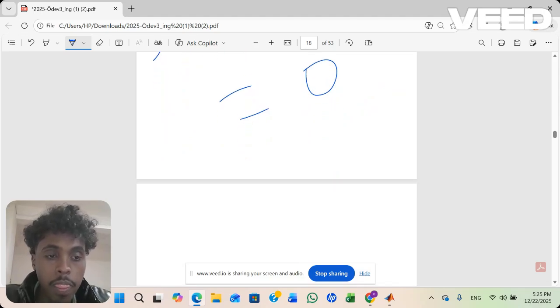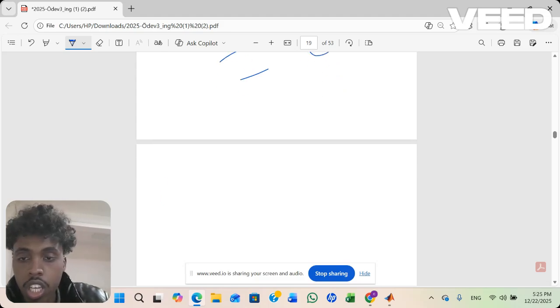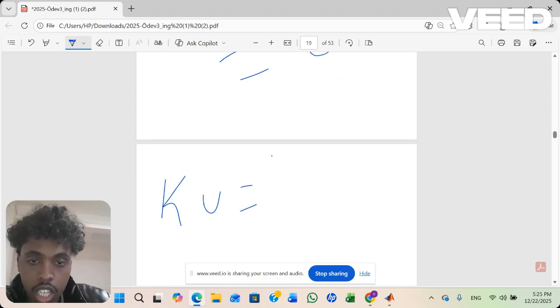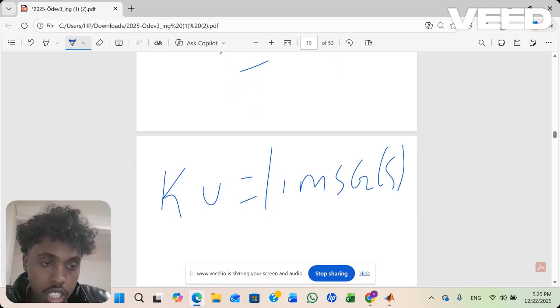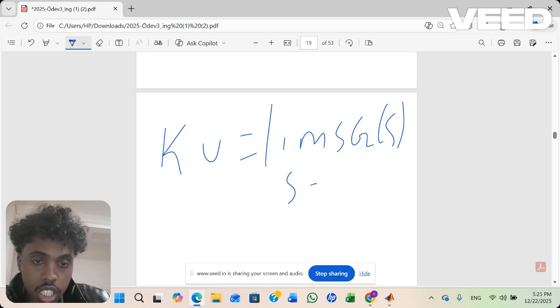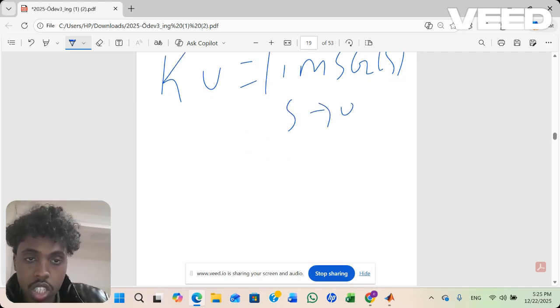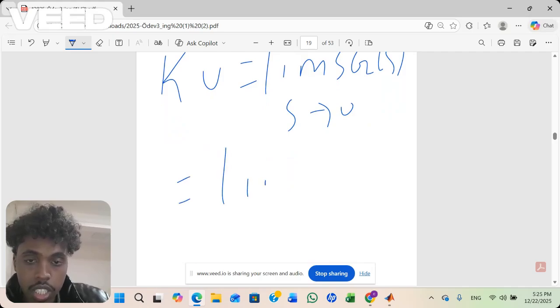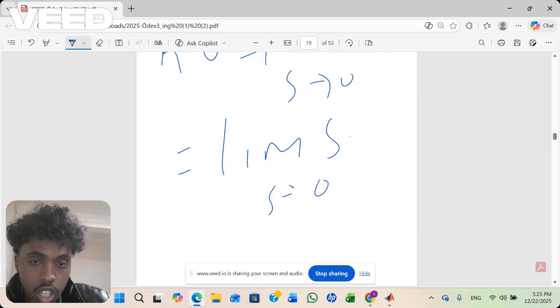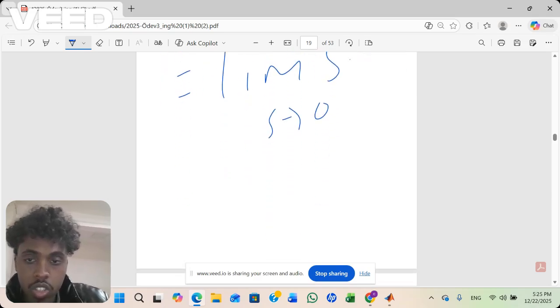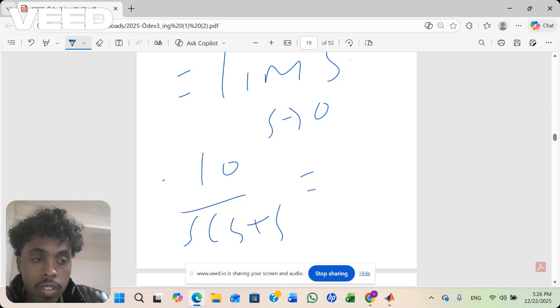So for example, Kv is the limit of s G(s) as s goes to 0, so limit of s times 10 over s plus 5, is gonna be 10 over 5.